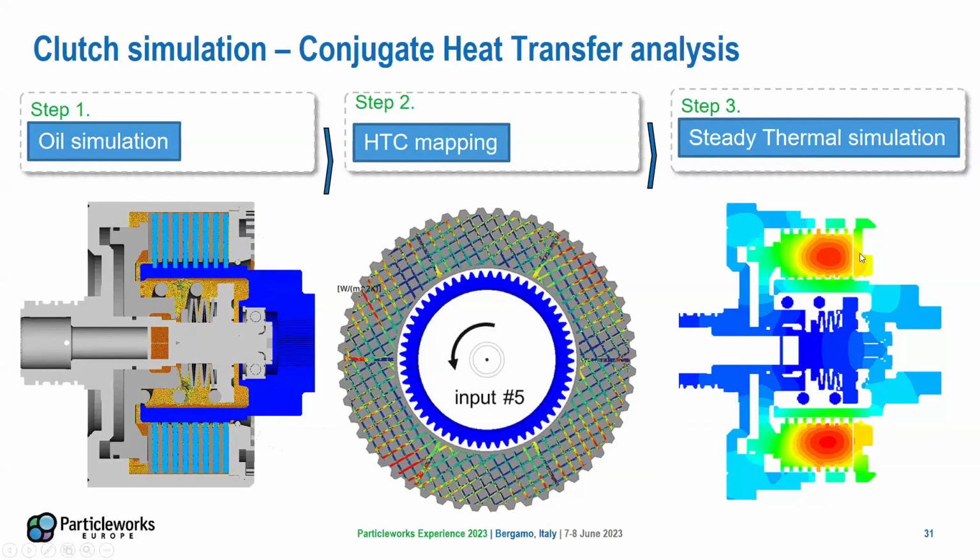Very interesting, because you can see an imbalance of heat in the disk area due to different flow distribution, because not all the channels are reached by the flow in the same way. Because of that imbalance due to rotation and so on, we could not, at least at the beginning of the design, provide distributed flow all around the disks.